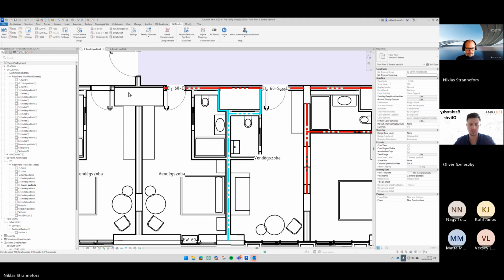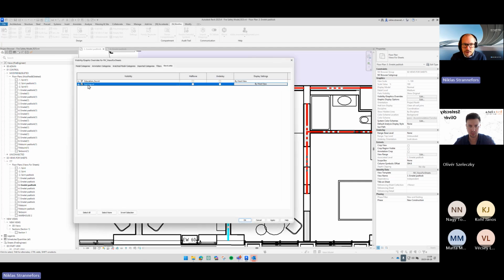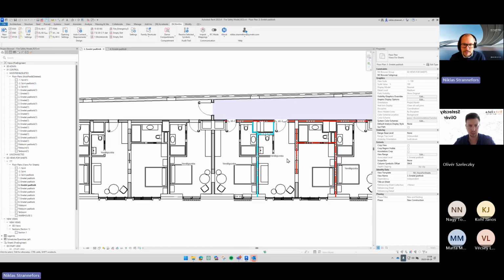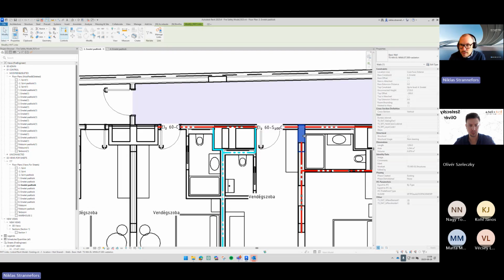Brilliant. Great, everyone. So what I did is basically lowered it, because every level is off by 830 millimeters, and just moved it down. So when you drag and drop and replace it and open, it's going to load and it's going to be looking good. So what I'm going to do is go into view template, because I turned it off. It's going to go to Revit links and turn the existing or structure model on again so we can see it. And then, okay. So we now get both the structural model visible and the architectural model. So we get a little bit of both.